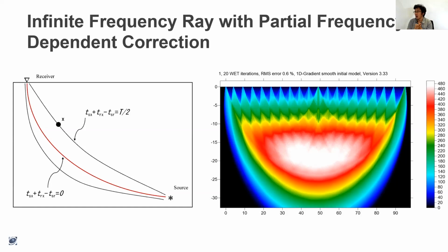Okay, so question 2, resolving small lateral variation from core stones. At depth, your core stone is going to need to be pretty big. At the surface, say your receiver spacing is 5 feet. If you had a 10-foot diameter core stone, you'd probably see that in the data. In fact, I have a good data set that I didn't add into this that would show that. So it just depends on where the core stone is. If you're trying to define the location of a core stone, refraction tomography is not what I would use, because I'm assuming the core stone is going to be near the surface, so I'd probably use GPR.